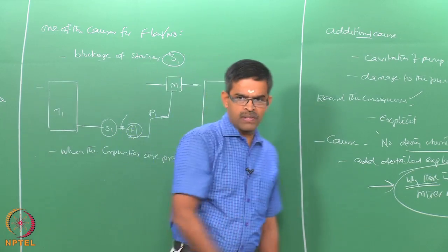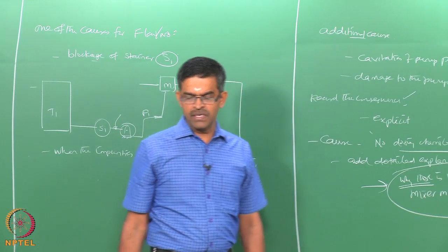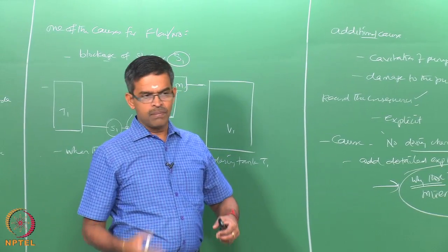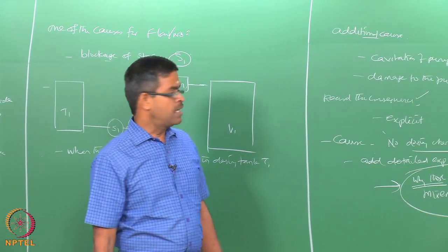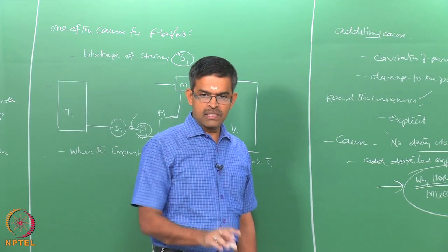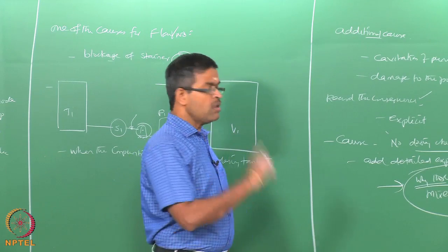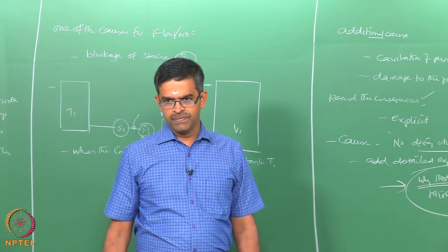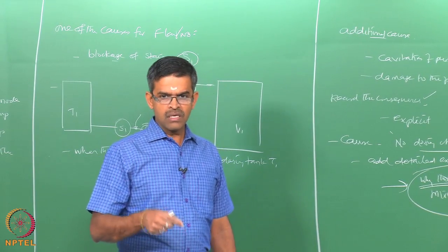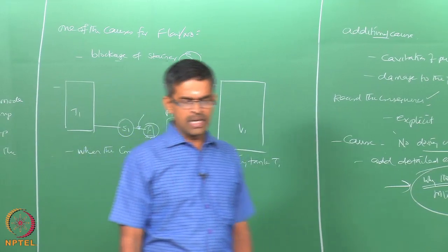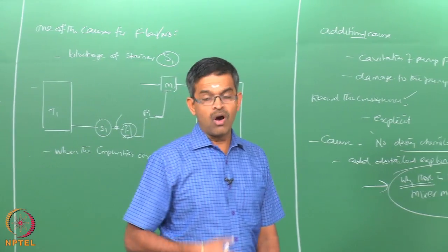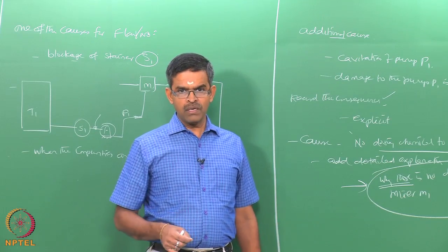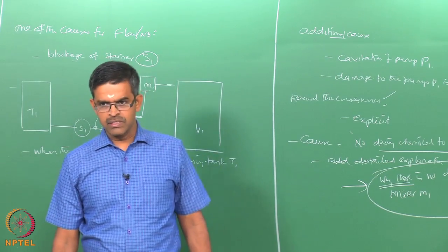When you assess the consequences in terms of safeguards present, do not try to take advantage of the existing safeguard present in the system in terms of, let us say, strainer S1, sensor, etc. Because with all these present in the system, you are identifying the deviation. So, do not try to say sensor not working properly. That cannot be actually a consequence or a cause for a function. Instead of that, you should try to recommend newly included things in the design.